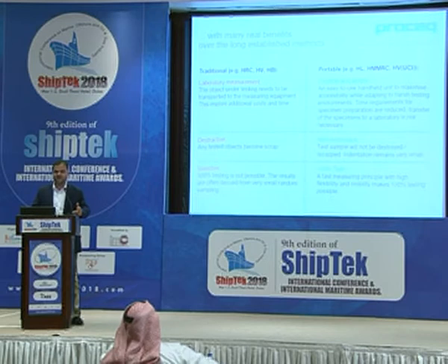This implies, again, additional cost and time. Any tested objects become scrap because it's a destructive test. Selective, 100% testing is not possible. In contrast, if you look at the portable, it's an easy to use handheld unit to maximize accessibility. It can be easily used for on-site testing. It's a non-destructive technique, so basically we are not preparing the sample, and we are not going to scrap the sample anymore. And the good thing is 100% testing is quite possible now on-site.